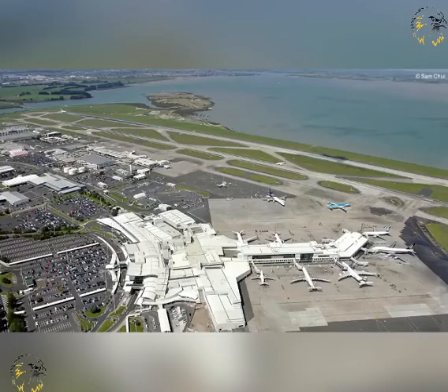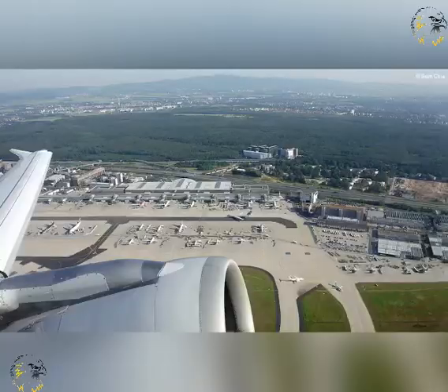The apron is the area of an aerodrome that permits the embarking and disembarking of passengers, cargo and mail, as well as allowing an area for the basic servicing of aircraft, without interfering with the day-to-day aerodrome traffic. The total apron area should be capable of allowing the expeditious handling of the aerodrome traffic at its maximum anticipated density.